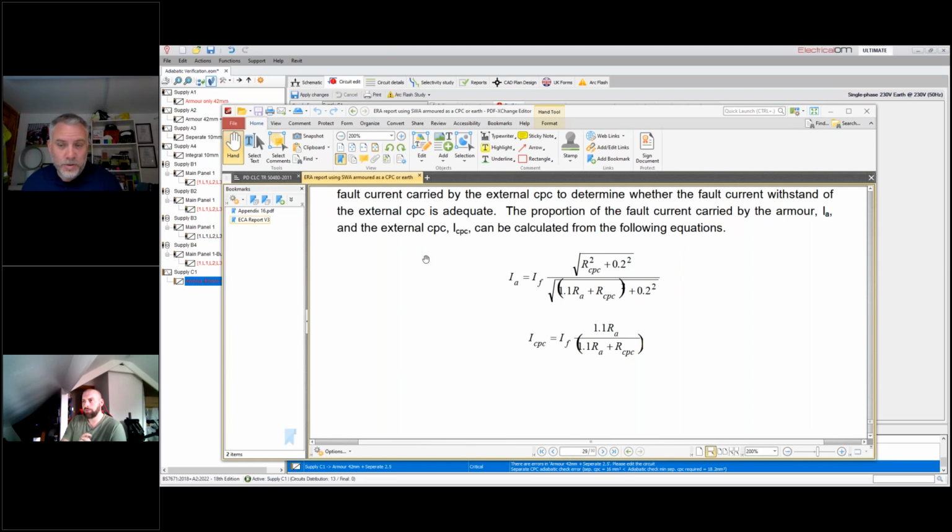I think that leads on to, and I'm going to jump around the questions, we said that we tend to run armoured cables inside, on ladder, on tray, all day long. We don't have to use the armouring as a CPC, but the only time we do is when we bury it in the ground. That's a definite yes, because we're using that for mechanical protection. It's an exposed conductive part, so we have to do that. And we've got a question about 522.8.10, when you put these in ducts. The only exception is if you do it in a duct. Yes, it's a brilliant question.